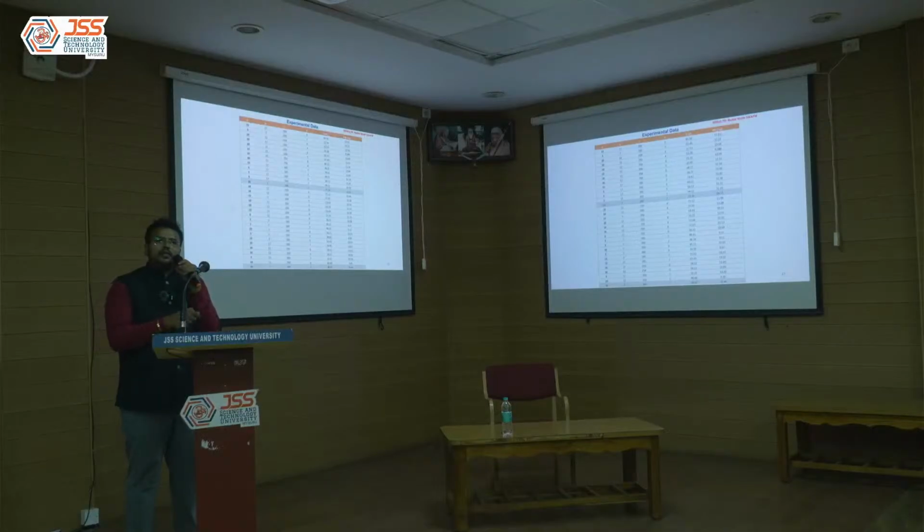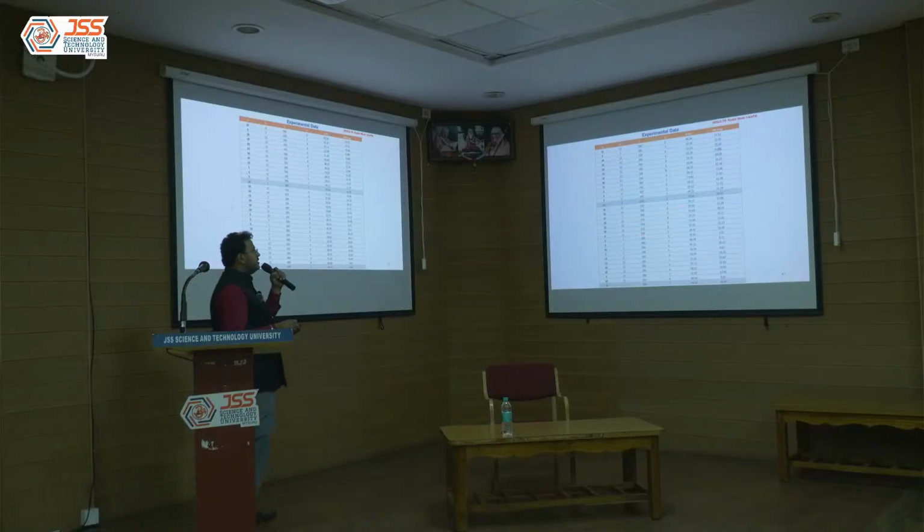We conducted some 31 experiments and we have recorded delta. Delta means it's a percentage improvement of roughness, which is higher the better. And MR means the material removed. So the quantity of the material removed before finishing and after finishing, we have recorded in milligrams. And based on the case study, we observed that the higher delta RA means the higher abrasive finishing we